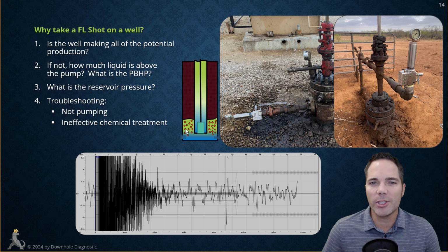And there's so much pressure down here and so much gas that's coming up the annulus that the well is flowing up the backside to some degree. So any chemical that gets introduced into the casing, just whoop, it gets pushed up and out and down the flow line. That chemical is not getting down hole.